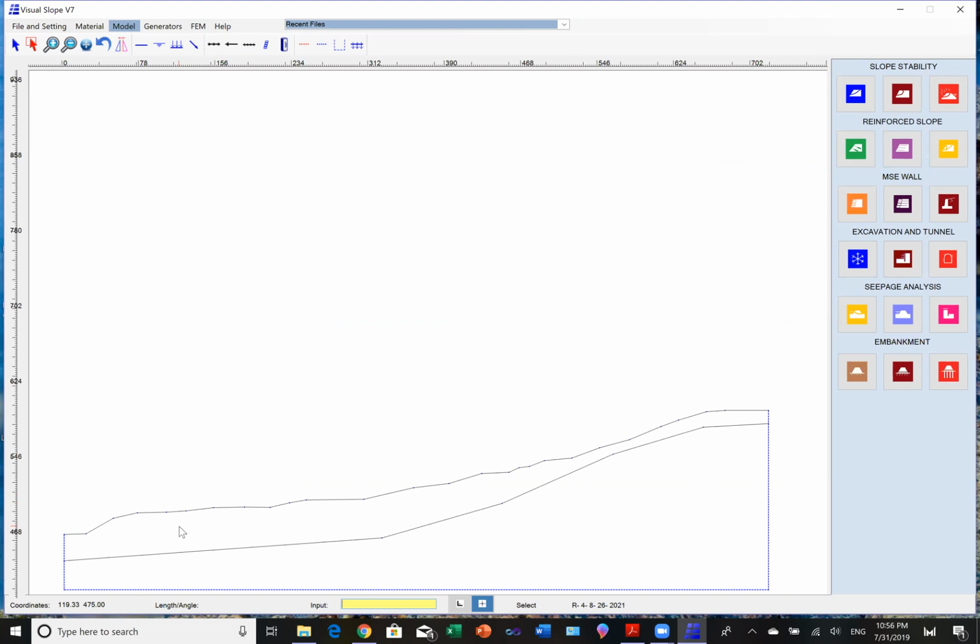And so, if you have material properties, you can put them in, and if you have a water table, you can draw it in, or you can just trace the water table the same way as the soil. So basically, this is how you use the tracing method to establish a model. Okay, the time is very tight, so I will continue on to the AutoCAD input method.